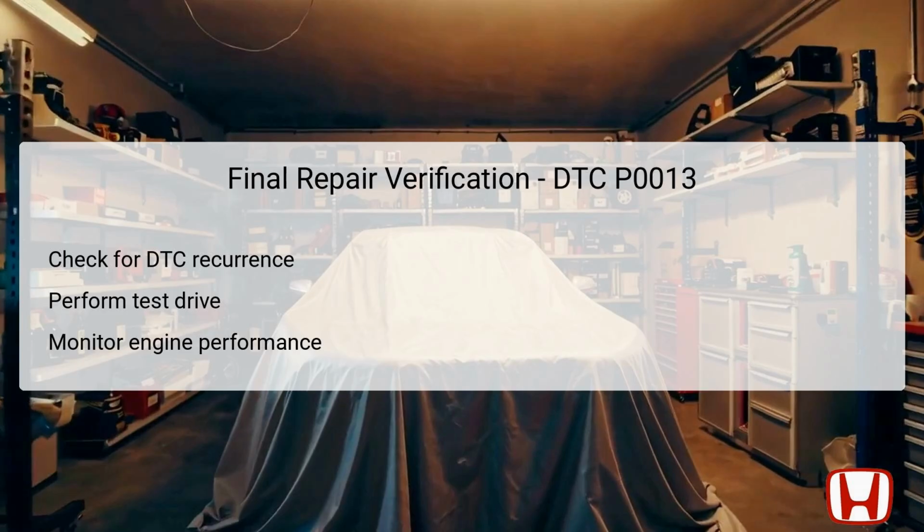Begin by checking if the DTC reoccurs. If it is cleared from the system without returning, that indicates a successful repair. Following this, performing a test drive under various conditions will allow you to monitor the engine's response, particularly in terms of acceleration, idling, and overall performance. This is essential for confirming that the VTC system operates as intended.